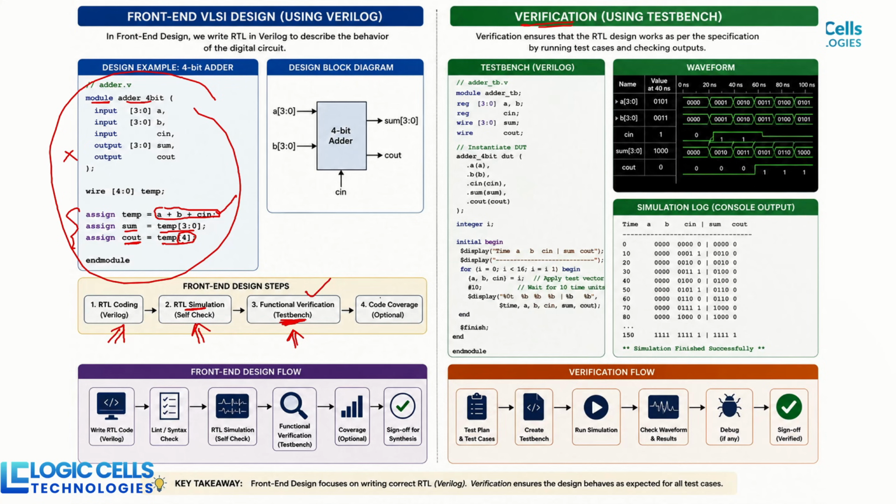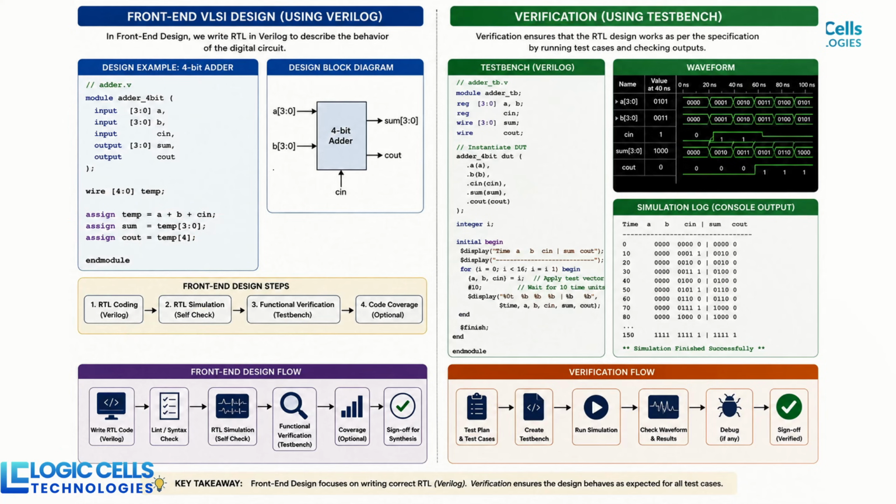After the simulation, you will check code coverage, which tells you how much of your design is covered through the test bench or through the different test cases you perform. That is the next verification stage. In these two stages, you need to write this kind of test bench. See module adder_tb. Then you declare internal variables here, and this is your DUT.